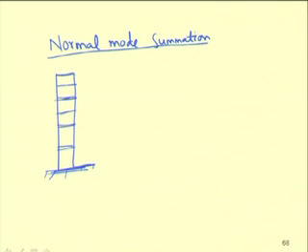For example, let it be a 100-story building. Then the equation of motion for free vibration will be m x double dot plus k x equal to 0. After the earthquake, no force is acting on the system, so if one considers free vibration, one can take this equal to 0.